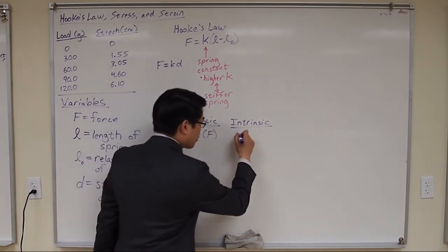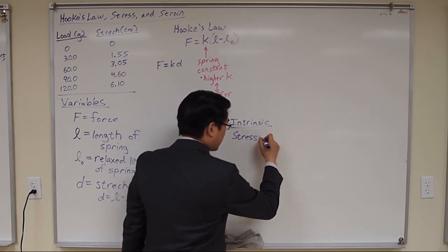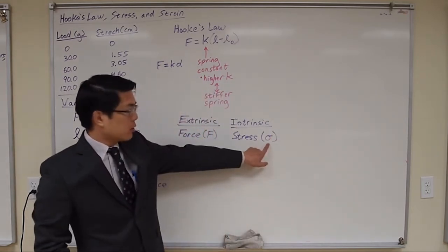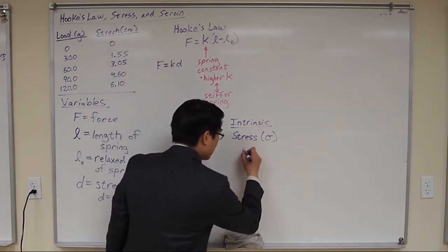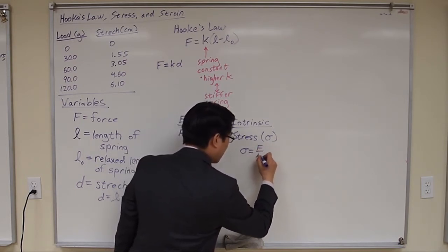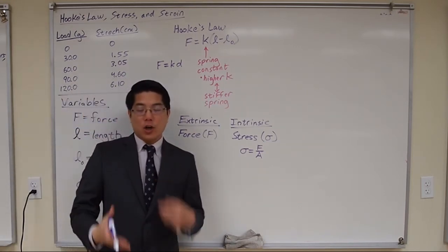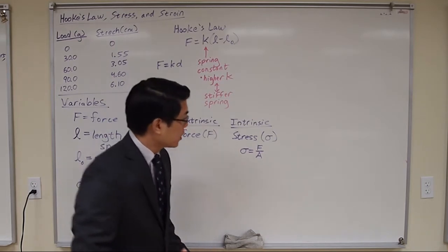It is called stress. And stress is abbreviated with the Greek letter lowercase sigma. The definition of stress is that it's equal to force divided by area. Specifically, the cross-sectional area perpendicular to the force.